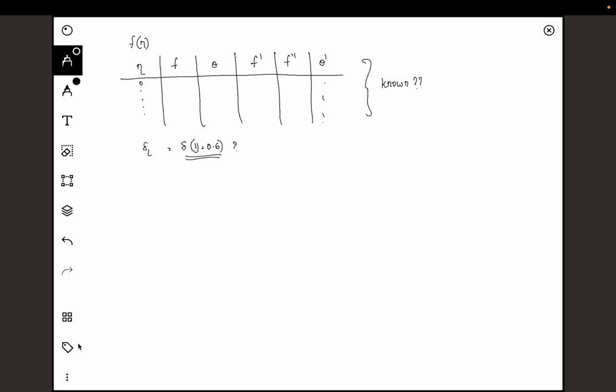Why do you think we will actually need the value of delta? If you recollect, in last week's lectures, when we were having a pipe flow, we had two different regions there. You have something called an entry region, entrance region, or entry length, and then you have the fully developed one. Even there, we need to know an estimate of delta, because if the diameter d is way higher than the boundary layer thickness at that particular length, then you can safely assume that you are in the entrance length region, right?